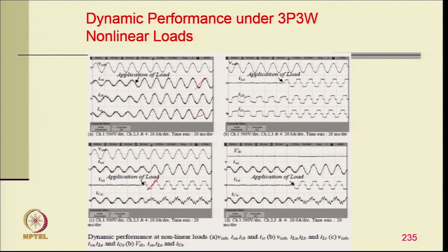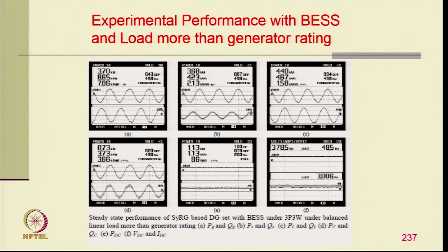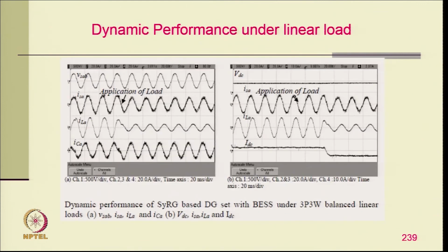It is not affecting the generator, and your compensator is providing active filtering when non-linear load is applied. And you can clearly see the sinusoidal waveform operating at unity power factor under different operating conditions, like when the load is reduced, and the generator current is still balanced and sinusoidal, and accordingly the battery gets charged or discharged.